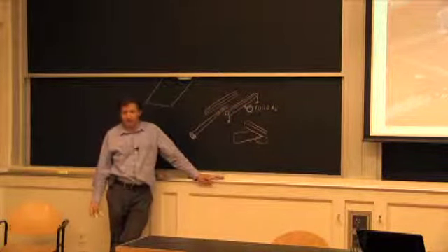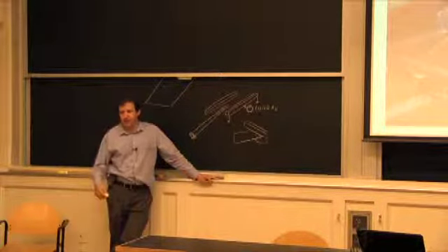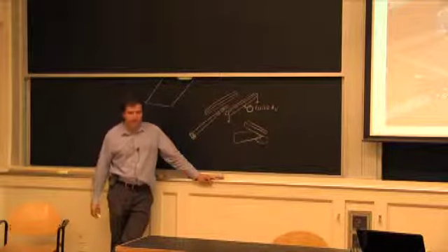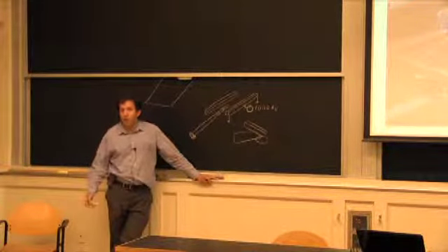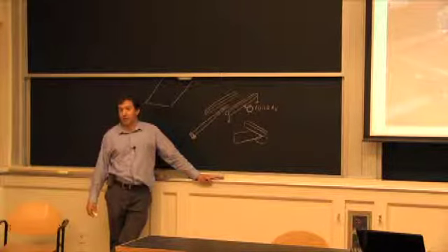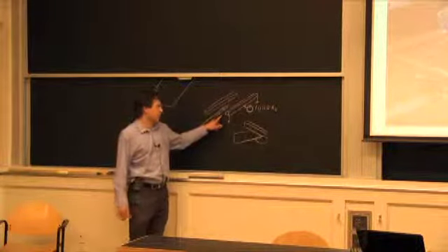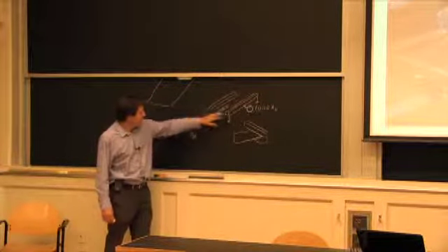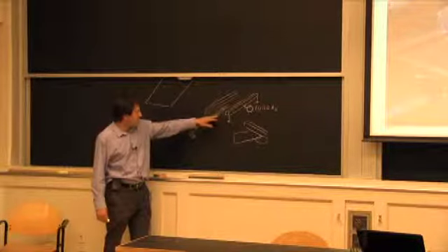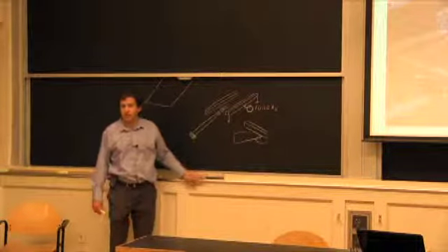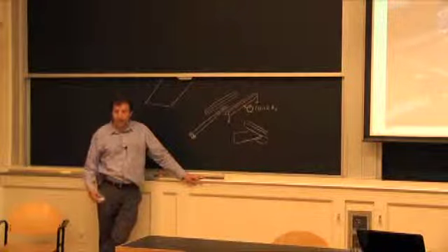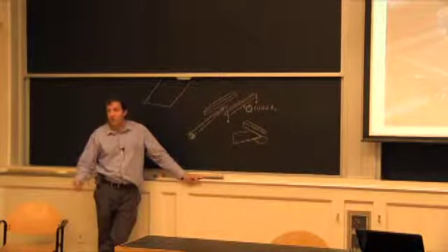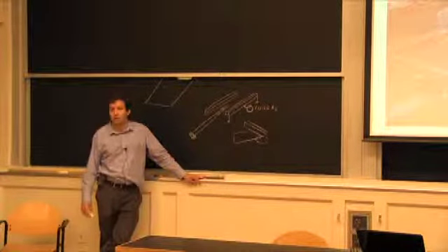And that tension yielding is something that in my case happened once. And that's how I know that I don't have any crack or any significant deterioration of that member. But it would be a lot easier to design this in ways where you put some more welding, essentially. And if you have welding in the tension zone and you start deforming it, then you're at risk of a premature failure depending on how the weld quality was.